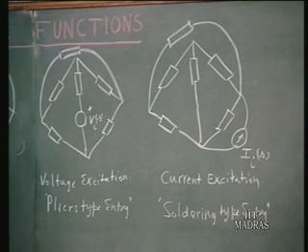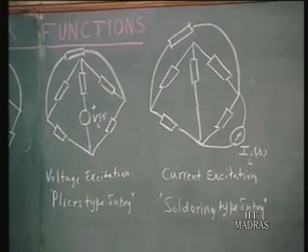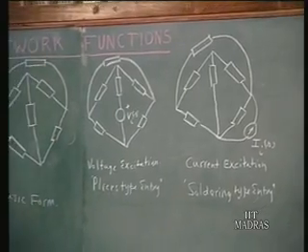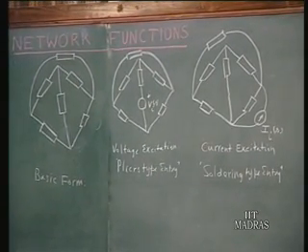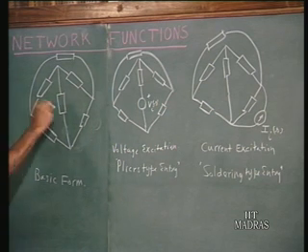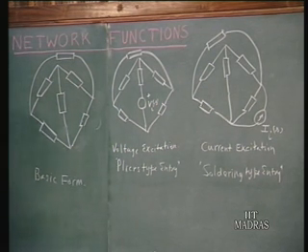So when you do that, no matter how you introduce excitation into what branch, whether current or voltage, and find out the response at any other point, then the poles of whatever network function you are talking about will be more or less the same, because the basic form of the network remains the same. So this is important to keep in mind, that for a given network configuration the natural frequencies are unique, and therefore no matter what type of network function you define, the poles are likely to be the same.